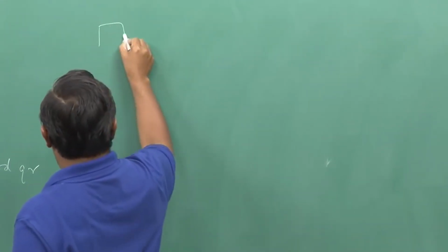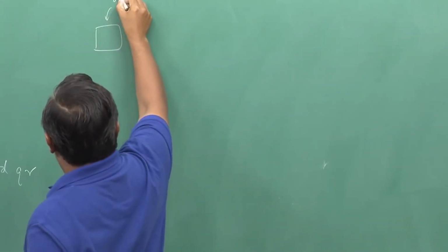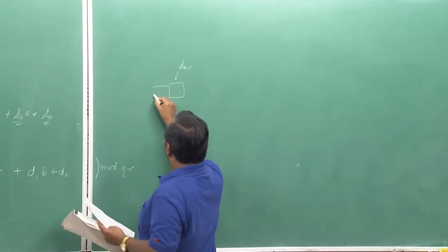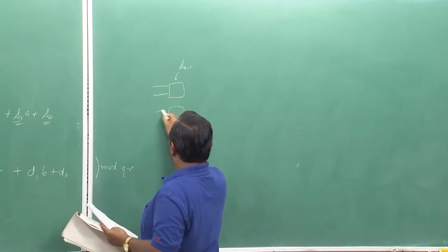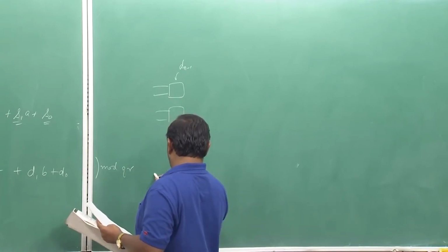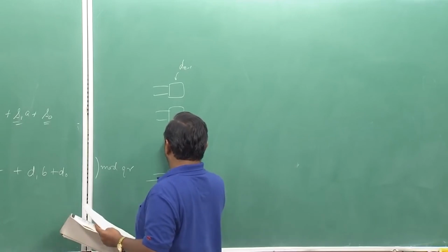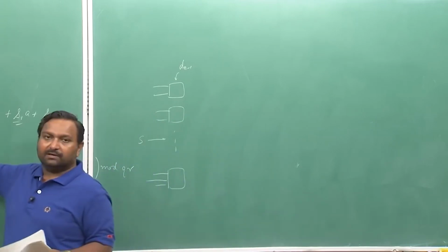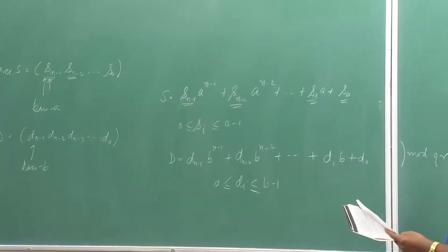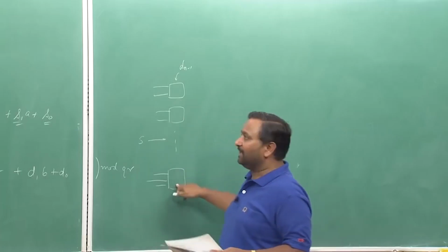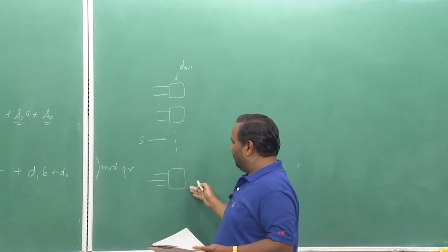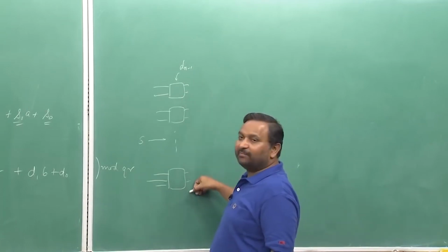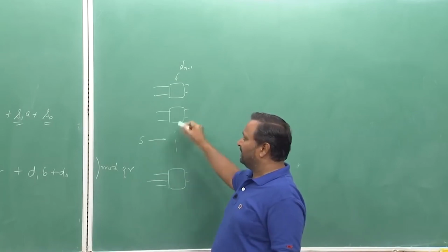In the first stage I am actually using d of n minus 1 for making the decision. So, if my source is somewhere here, somewhere in between, I call it S, which is represented by this number. So, this number will be now connected to which one of these switches? I need to find out after switching what will be the output number, what is the number here, what is the wire number from top to bottom when I am counting, to which this packet will be routed.